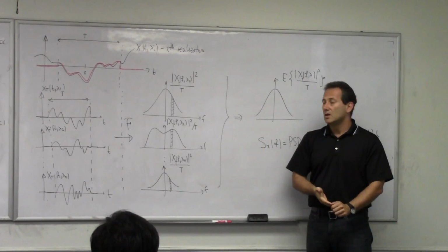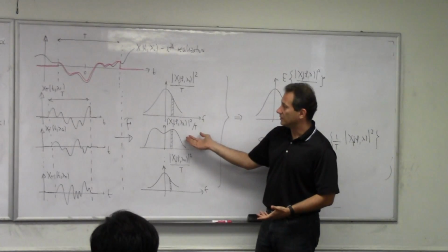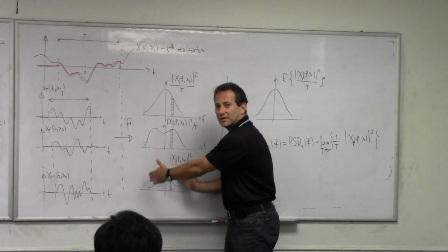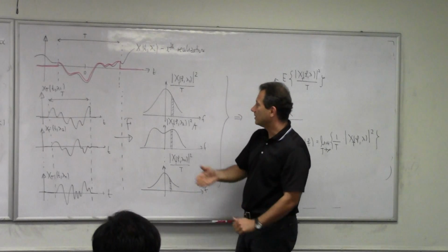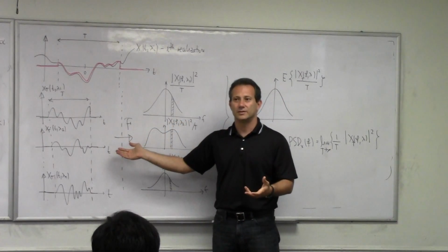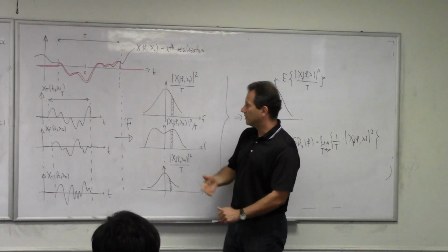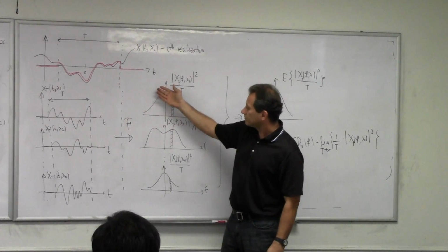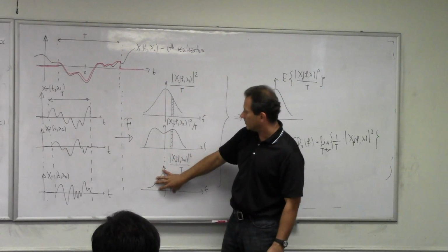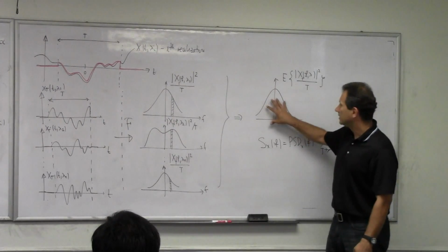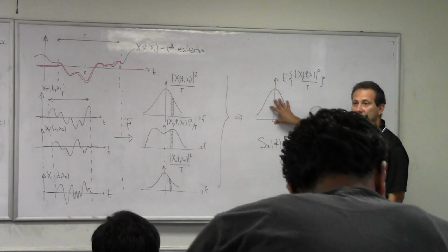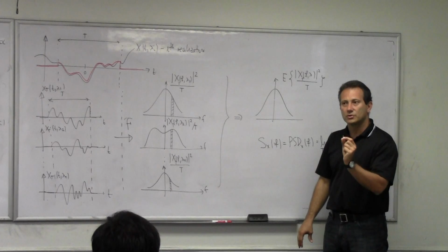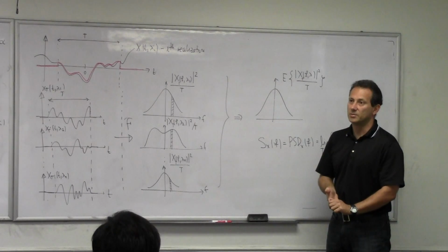It turns out here I have exaggerated a little bit, right? If this is some sort of ergodic stationary process, then chances are these are going to be very, very similar, right? Because remember, the Fourier transform is also a form of averaging, where I'm taking an integral transform of my signal. So I will probably get very similar graphs here, and then when I average them, I'm going to get a single function of frequency that tells me what is the individual contribution of a particular portion of the frequency domain to the building of this kind of process.